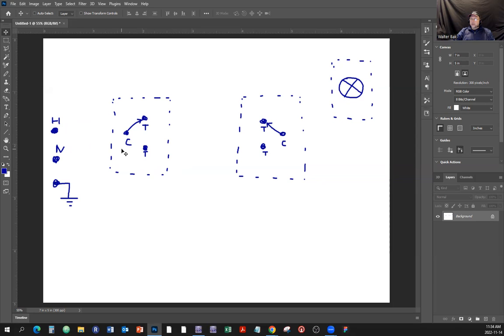Sometimes the power is going to be provided to the second box, which is the box in the middle of the whole run. And sometimes the power will be provided to the load box of the whole run. We're going to have to connect it in the same way, but the wires are going to have to be routed a little bit differently. But this is the simplest way, just to show the idea of the functionality of a three-way switch.